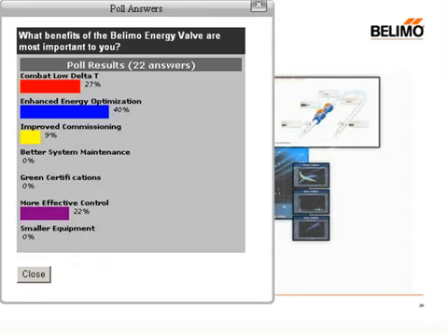Okay, we have our next question here. Are there any advantages over VFDs, variable frequency devices? This comes from Mark Miller. I think these valves basically make the VFDs much more effective. The idea that the coil is being controlled properly allows the VFD to drop down to much lower flows than it would normally be operating with when it's just being run on whatever delta P that you believe you have to have on the system.